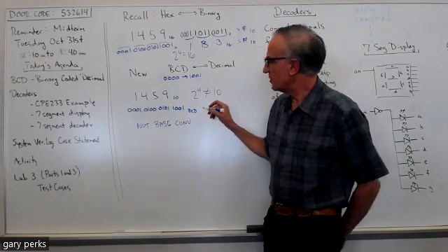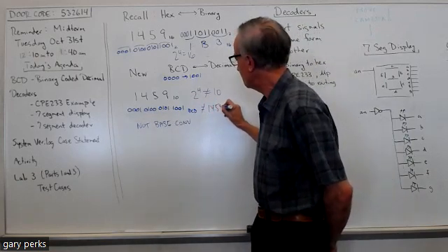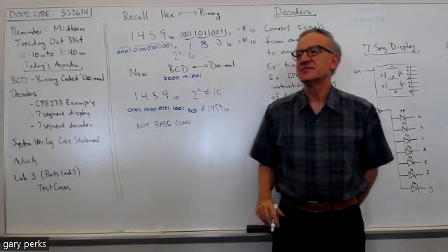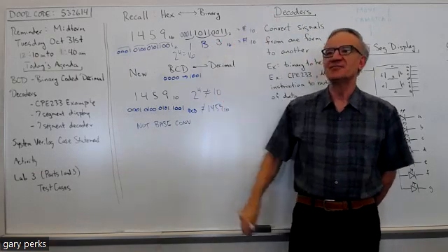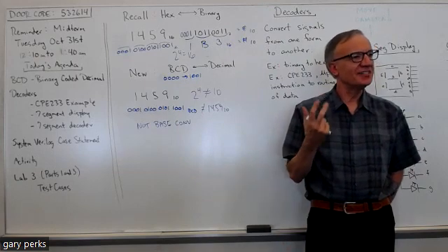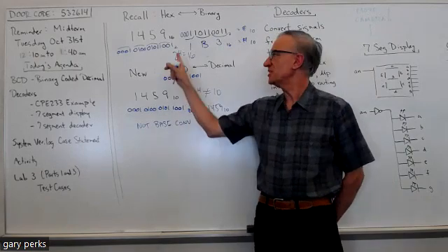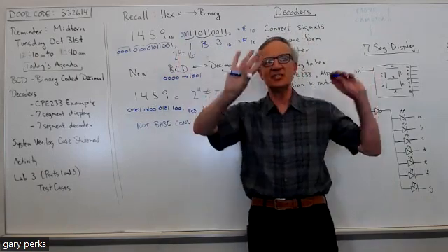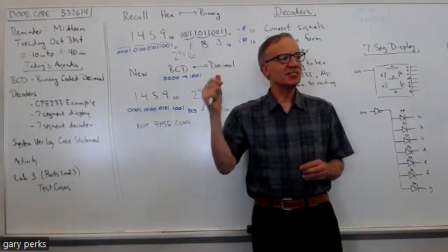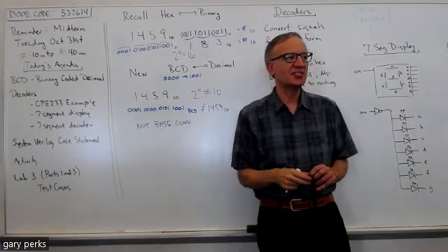Okay, like if you do the binary for this, it's not going to equal 1459 base 10. It's going to equal what it did up here. Okay, so that's the key thing. Once people learn about this BCD, they start confusing it with this, but they're two totally different things. One's base conversion, one's just representing a base 10 number with bits for each digit.